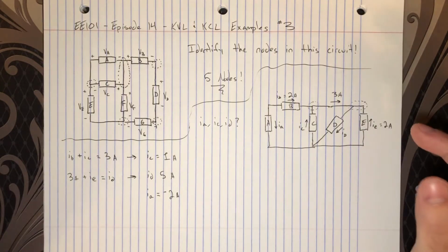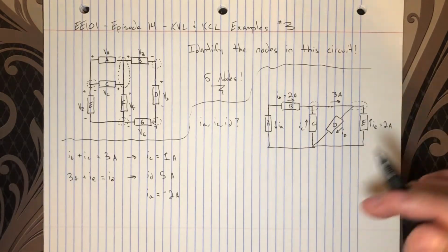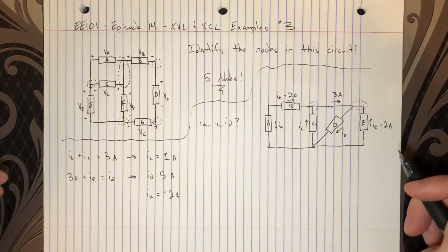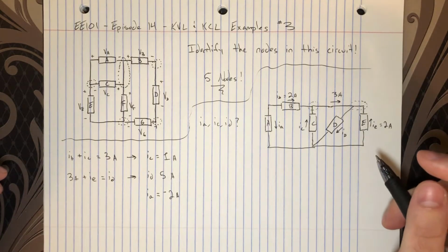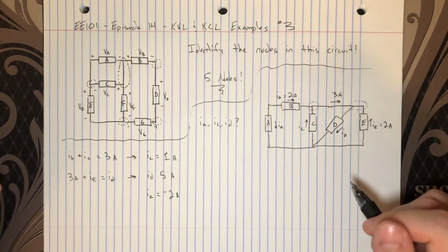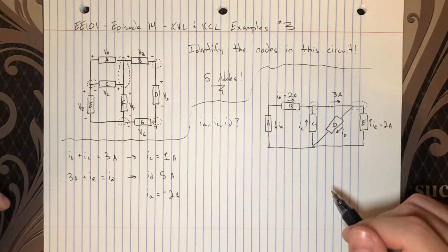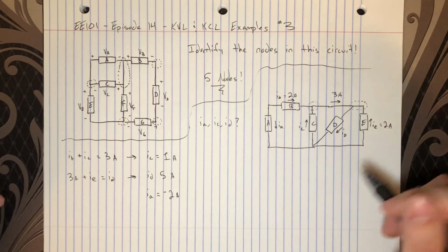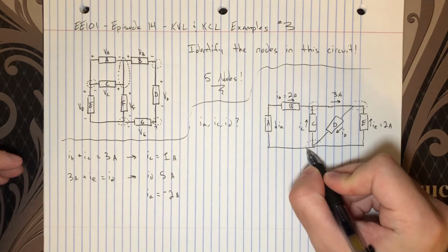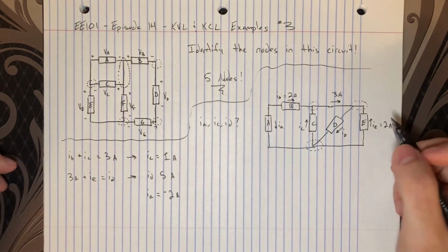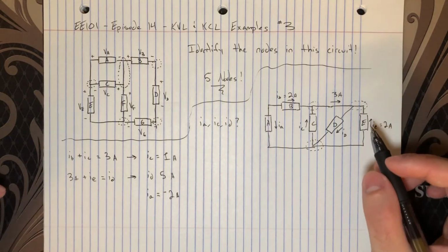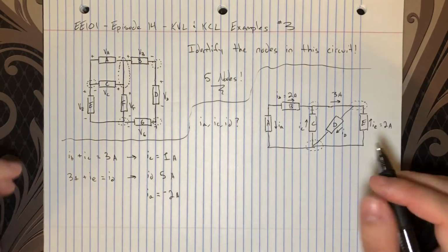And one more thing we can do, and that you should do, especially when you're starting out in circuits, is find ways to check your work. And if you paid attention, you'll notice that there's actually one node that we didn't even use in this problem, but we can use KCL again just to verify the validity of our result. So there's a node right here where A, C, D, and E all interact. And let's perform a KCL there, and that should work out.